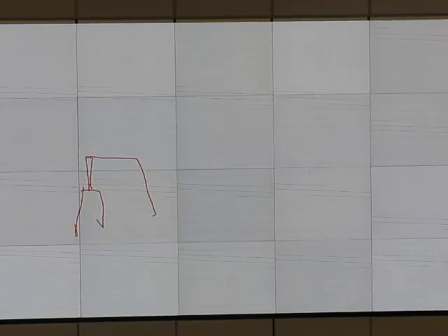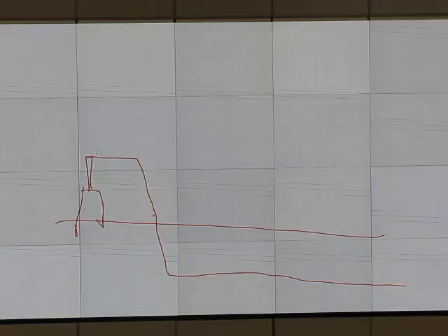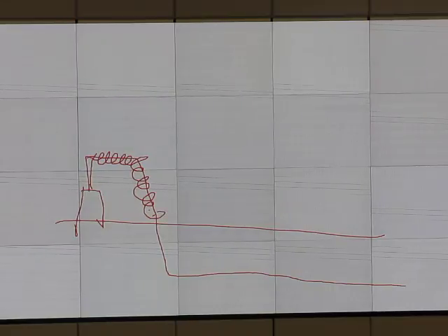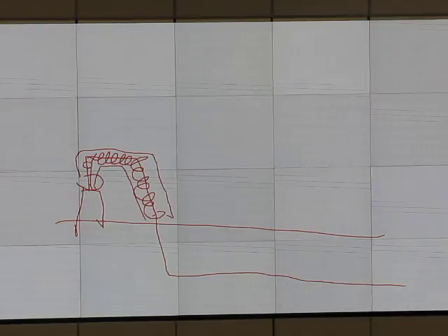Bury the pipe. Your wellhead looks like this, right? Some part is above ground. So this is ground level, you go underneath it. Okay, buried it. And the part that is above, put the heat trace. It's a coil that has a thermostat. When it's cool, it's on, so it uses the power from the grid. And you insulate it. You put the insulation wrap around this part. So the part over here, you don't have any problem.